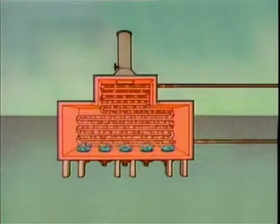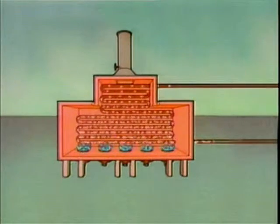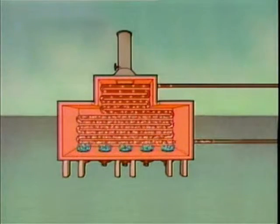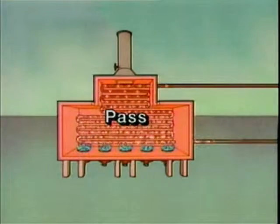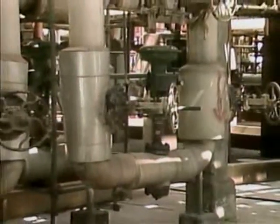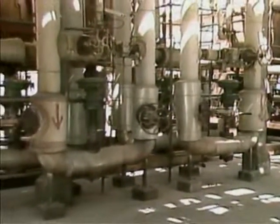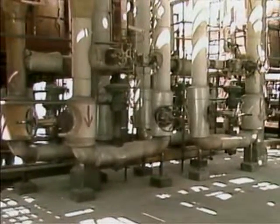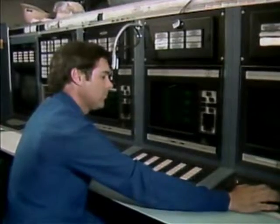The route that the process fluid takes as it flows through a furnace depends on the design of the furnace. Each continuous, uninterrupted path that the fluid takes is called a pass. This furnace is a single-pass furnace, but many furnaces are multi-pass. The flow rate of process fluid through a furnace is regulated by valves. There's usually a control valve for each pass.